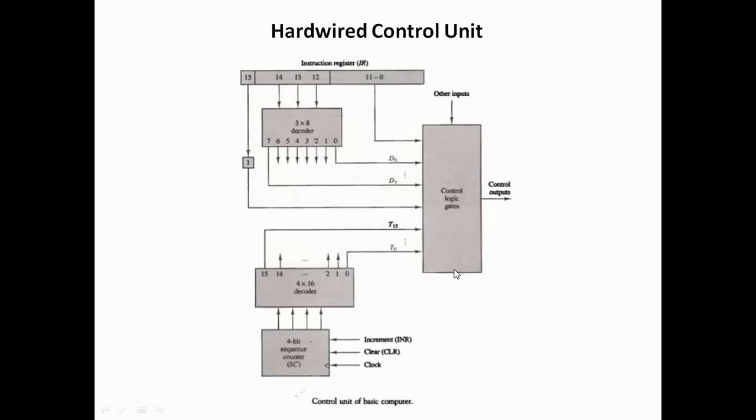which will be provided, because every single unit in a computer runs on timing signals, clock pulses, and clock pulses are usually generated by a master clock. The master clock generates clock pulses. The same clock pulse goes to every single register in the processor and every other circuit in the processor. But we can control this clock pulse like this, using a simple sequence counter and a decoder.